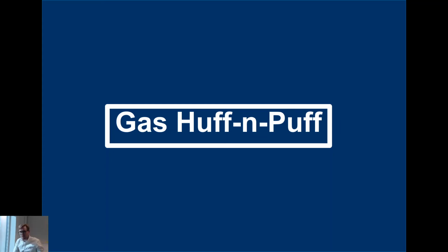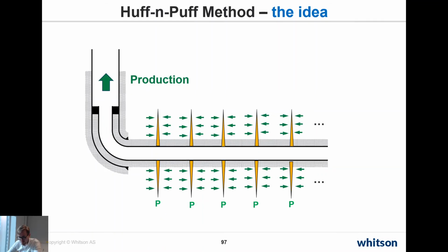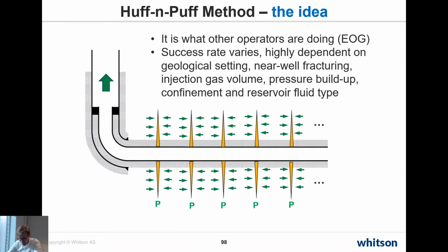Okay. Good. So the next topic we'll discuss a little bit more in detail is again back to gas huff and puff. We discussed the process. This is the third time we see the schematics. But on a generic basis, that's what all the other operators are doing. Success rate varies, and it's highly dependent on fracturing, injection gas volume, pressure buildup, confinement, reservoir fluid type, geological setting, etc. So fairly complex.